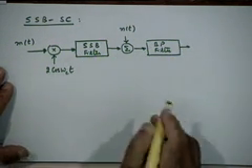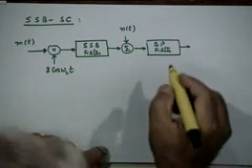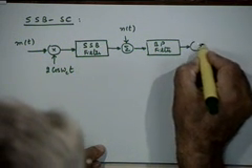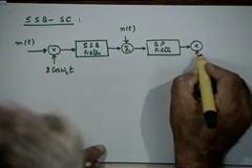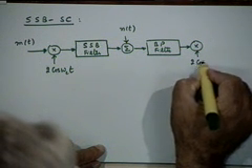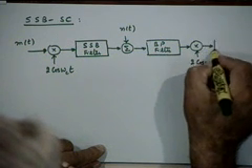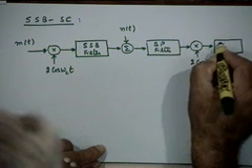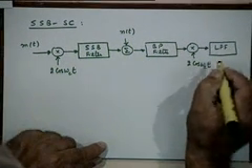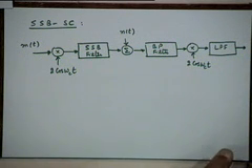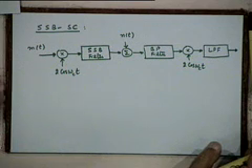Sorry, the sideband is already removed, you are just selecting the required carrier frequency. So, a selection filter, and then the demodulator, which is again a synchronous system followed by a low pass or baseband filter, and that is your final output. That is your overall system which you need to analyze.